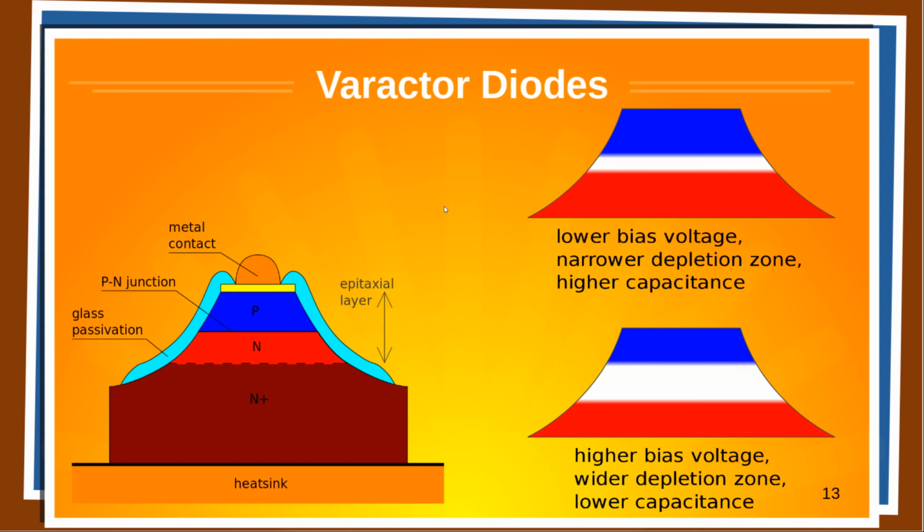They're in the picofarad range. Now, that's what I was going to say, because the reason we use larger capacitors is that with a component, you're not going to vary that width very much. Like a depletion region, you're not going to change the overall capacitance very much. Well, and that's why for a transistor, for instance, the base emitter is going to have 5, 10 picofarads of capacitance, which is that depletion region. Right.